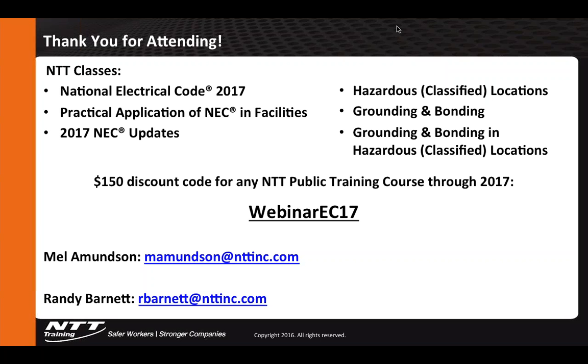One more question. Why do they need a new article on photovoltaic systems? That's always one of my issues. I go, why do we need a new article on that? And as Mel mentioned, we're talking 5 megawatt systems. So we're talking some huge photovoltaic systems and different technology, different types of equipment for installation, which was not covered in Article 690. Trying to use Article 690, the existing article on photovoltaic systems, just simply wouldn't work and created confusion. So they separated those into 2 separate systems, the breaking point being 5,000 kW and rooftop mounting and so forth. That's why the technology has changed. The work is already being done in the field, and we needed to jump on board and help those folks out.